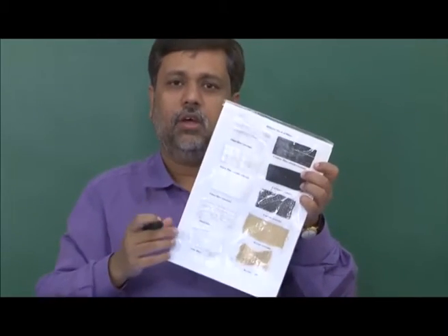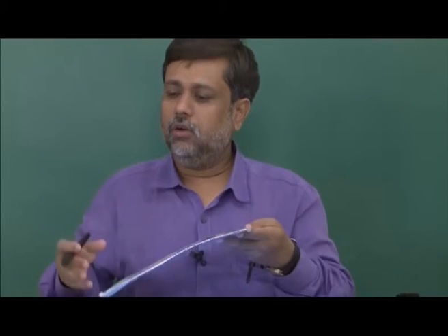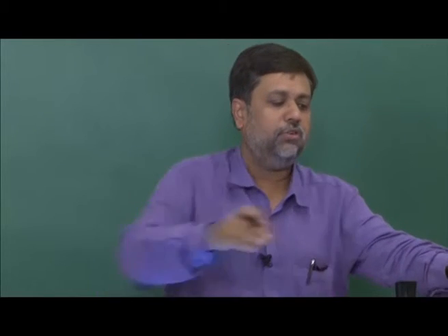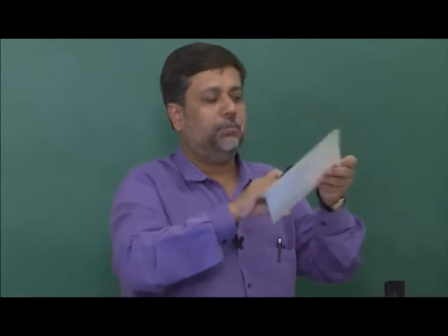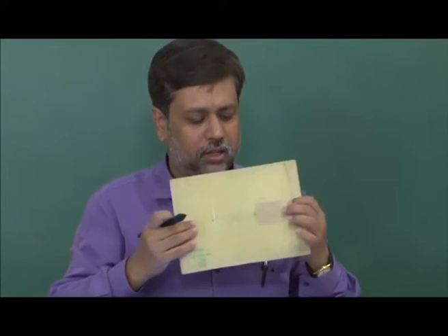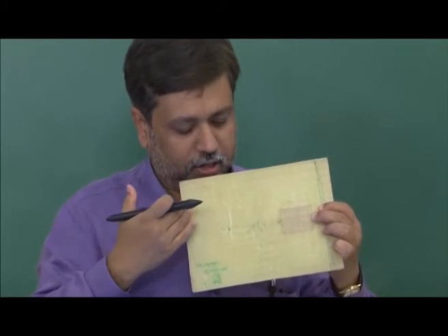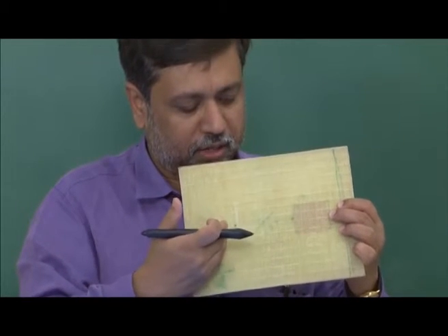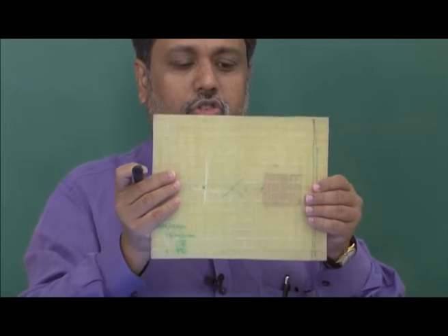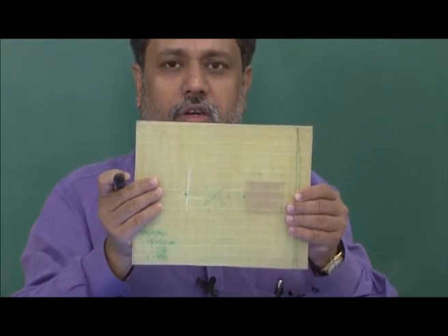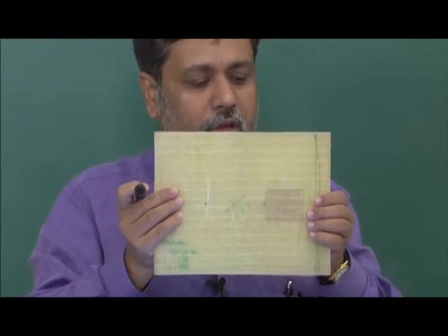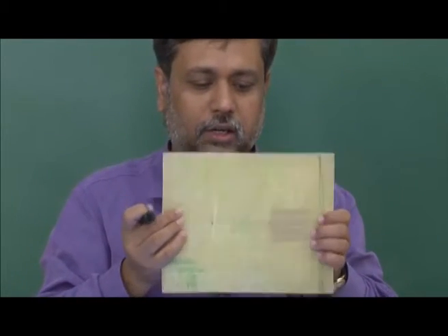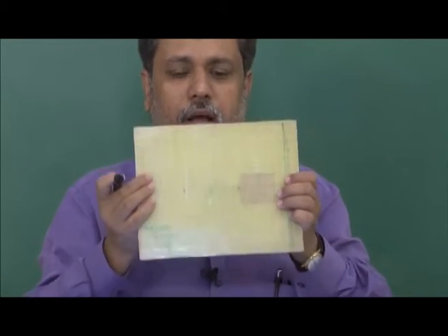So, these are the glass fibers, and then if I apply the epoxy resin, it becomes a composite, and this composite will look something like this. You can see that the fibers are there inside, and then there are layers of epoxy resins, the polymeric resins that are applied, and finally you get a strong structural composite out of the whole system. Of course, there is also one embedded damage in it, a rectangular damage. I will talk about such a thing at a later stage, but this is an example of a glass fiber reinforced composite.